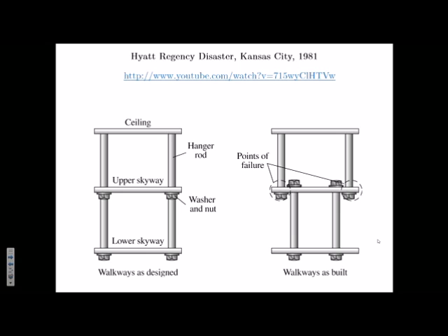So the design engineers, the guys who designed this, basically ordered about 20 feet of thread to be cut from here to here, right, from the lowest nut to the middle nut, so that you could push the nut up. If you don't have threads over here, how are you going to push the nut to the middle? Of course, that's a lot of cost, right? You have to thread this 20 feet of rod, both of them.